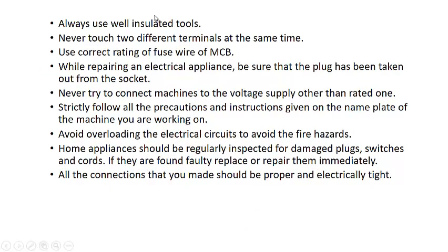Always use well insulated tools like pliers and screwdrivers. They should be well insulated. Never touch two different terminals at the same time, because they will complete the path through your body and you will get an electric shock. Use correct rating fuse wire or MCB.